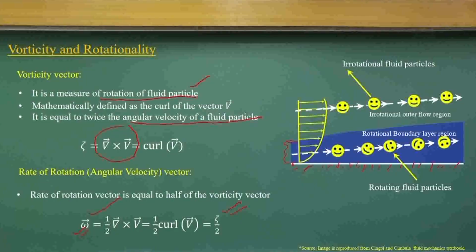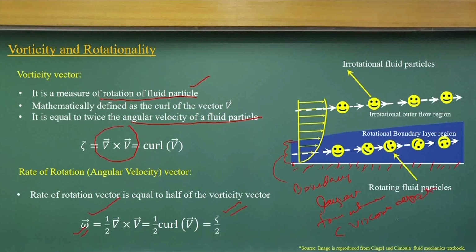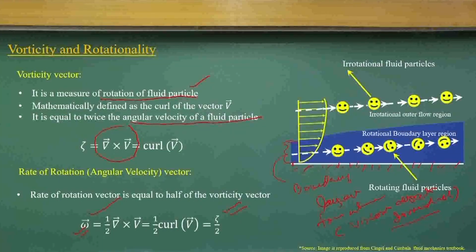So, in this figure, when the fluid particles enter here, there are large velocity gradients, and there is turbulence. The boundary layer formation is the zone where viscous effect dominates. In those regions you will see vorticity, or the cross product of del and V will show the vorticity, and graphically you can see it. It is just vorticity. It is a rotation.